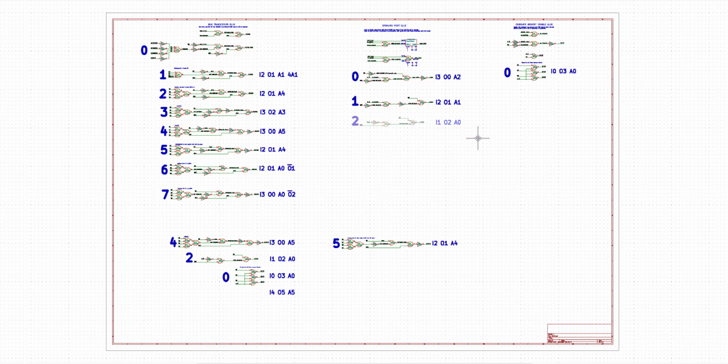And option 2, option 0. So option 5, 2, and 0, now I only need 3 inverters. I need 6 OR gates, so that's 1.5 chips for that, but I only need 1 quad 2-input AND. So that's 2, 3, 4 chips.